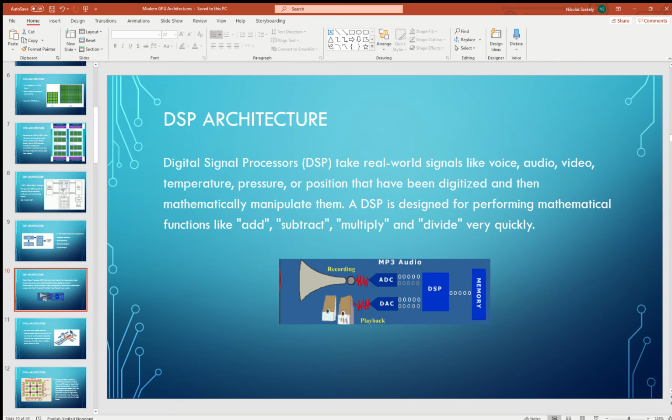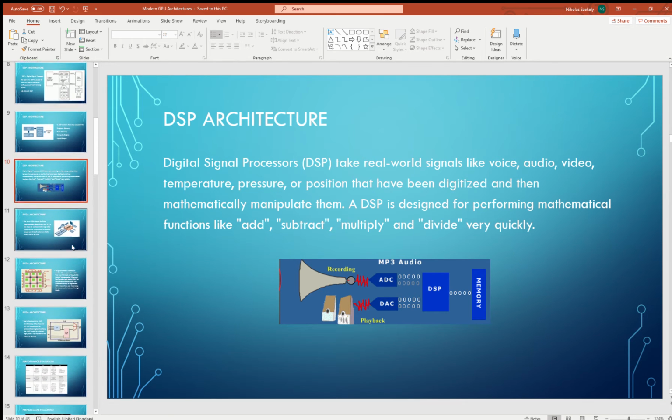The SHARC is a Harvard Architecture word-addressed VLIW processor. It knows nothing of 8-bit or 16-bit values, since each address is used to point to a whole 32-bit word, not just an octet. It is thus neither little endian nor big endian, though a compiler may use either convention if it implements 64-bit data or some way to pack multiple 8-bit or 16-bit values into a 32-bit word. Analog Devices choose to avoid the issue by using a 32-bit character in their C compiler.